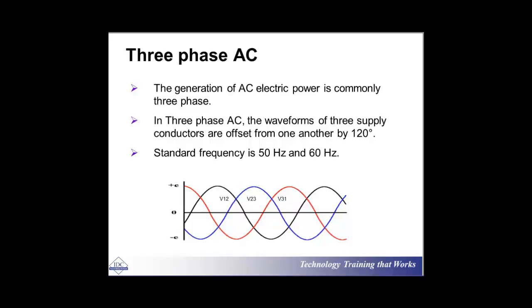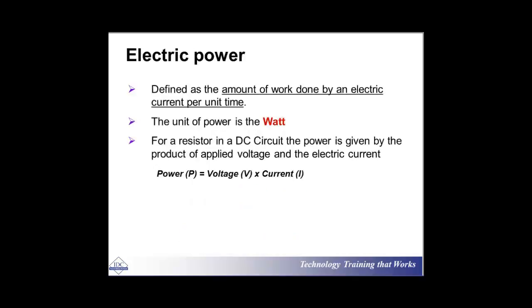And when you have an unbalanced system, that's going to be very bad, because you have unwanted or leakage currents. You will have overheating of the machines. You will have damage to, let's say, household appliances. So when we are dealing with three-phase and single-phase, we have to be very, very careful.